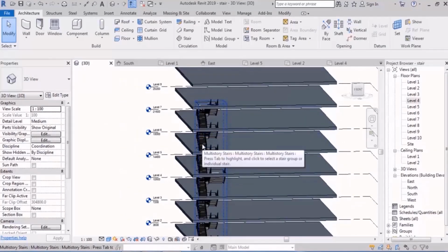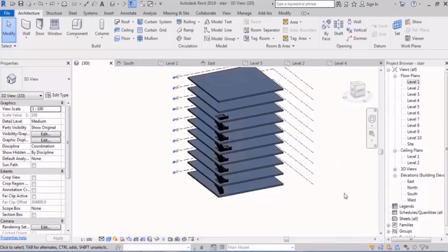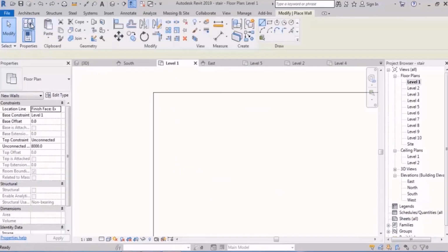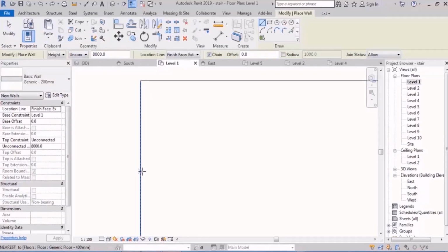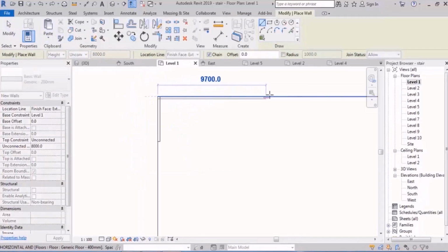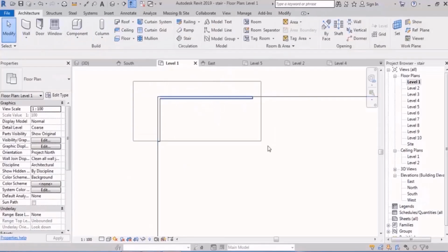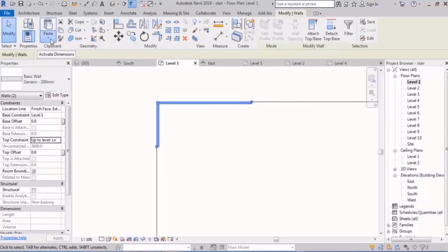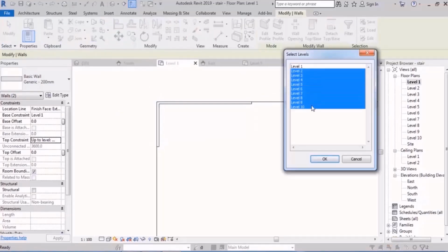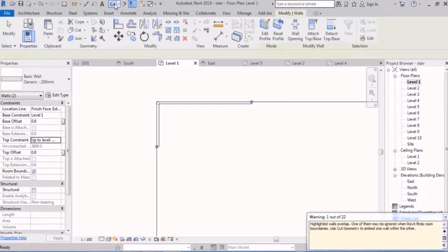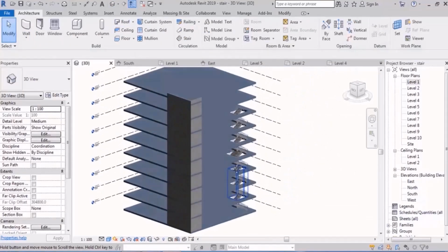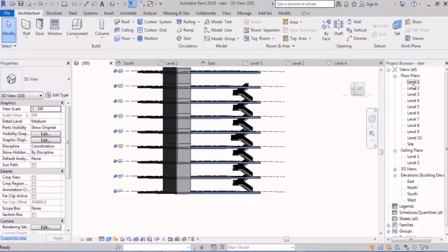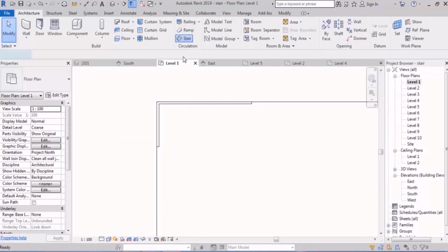There's another thing that I need to tell you, and you need to pay attention to it a lot, right? So, I pick the wall, and imagine I want to draw a wall in this corner, for example here, and then I want to draw some stairs. So, I copy this up to level 2, and then paste it up to level 8. And now I have nothing to do with the connections and attach and join. Then I go to level 1 and draw a staircase. Pay attention.